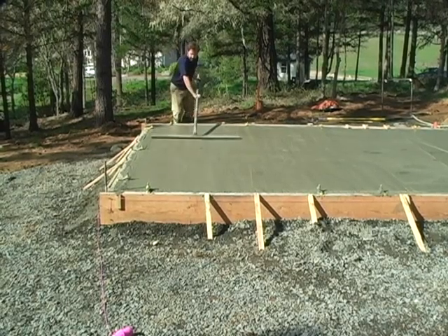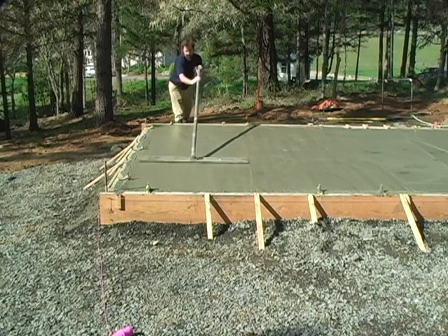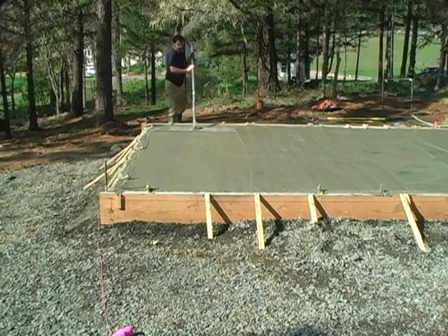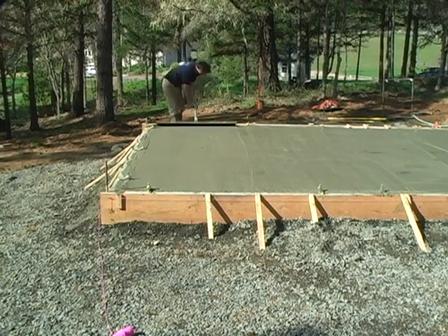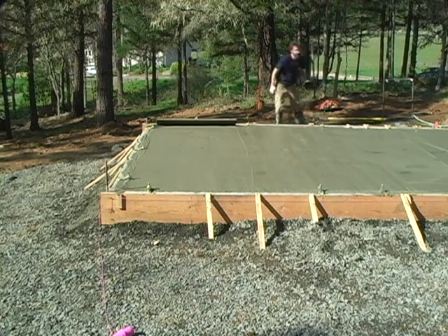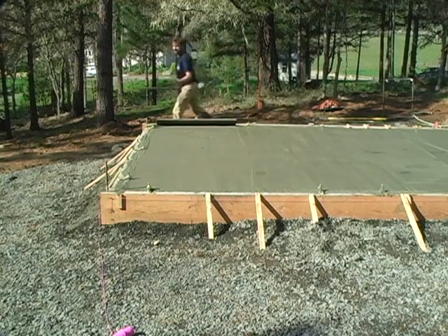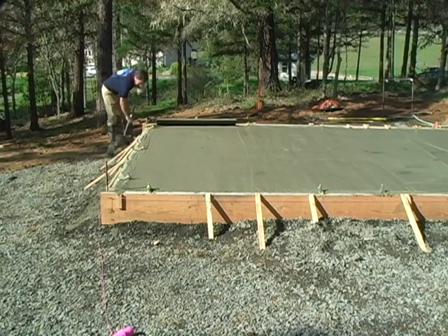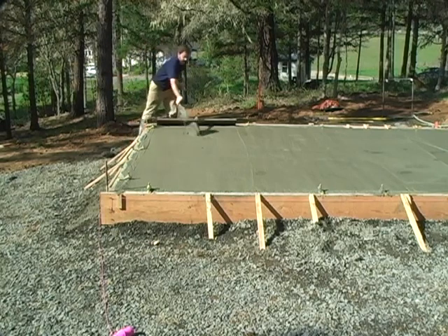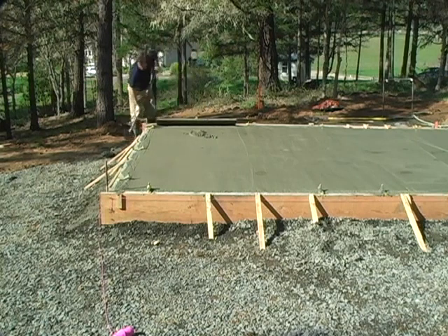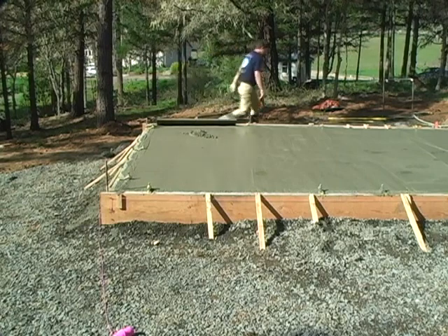So now moving in the opposite direction from where I was just troweling, I come back across the same area. Now that area is low. So what I had done when we were screening, when we got to the end of the foundation, we had too much concrete. I made a pile of it so that it's still clean, and I can get this in here and fill this hole. I'll give it, that's probably enough to get both of those. And then I'll tamp this down again.